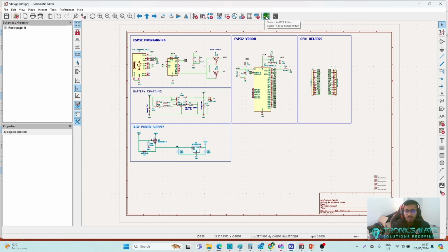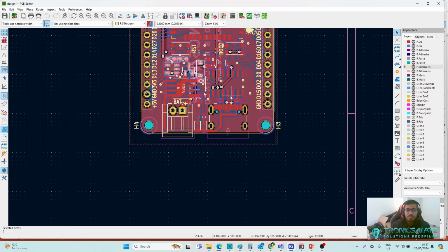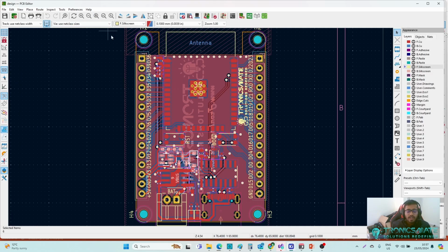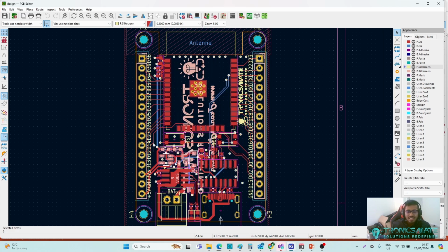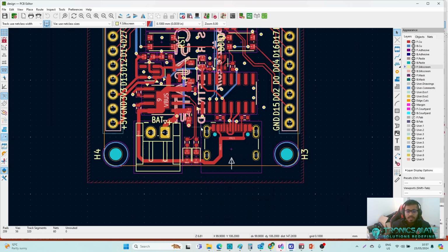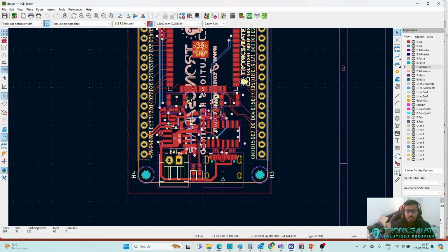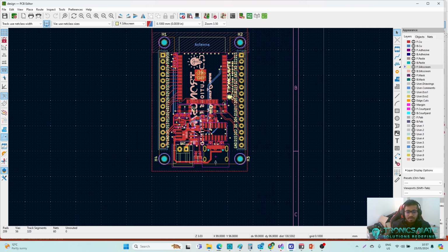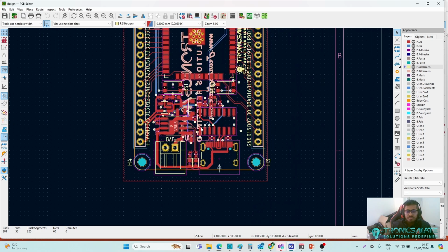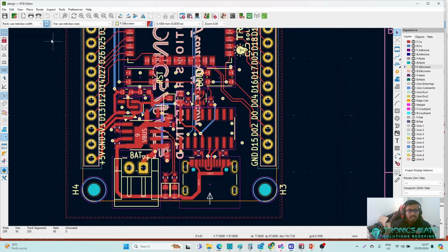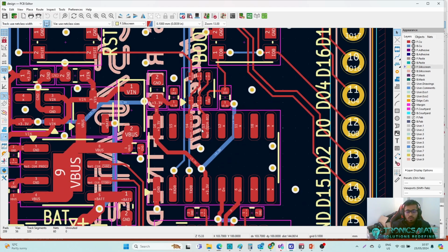I know the video is longer than expected, so I'm going to explain the PCB design very quickly. Since I'm providing the Gerber files, you can manufacture the PCB, but I will explain some important things you have to consider. For example, the footprints and placements should be very clean, and whenever you are designing a PCB, spend more time on placing the components, not the routing. Once you have placed the components well, you can route the PCB very neatly.